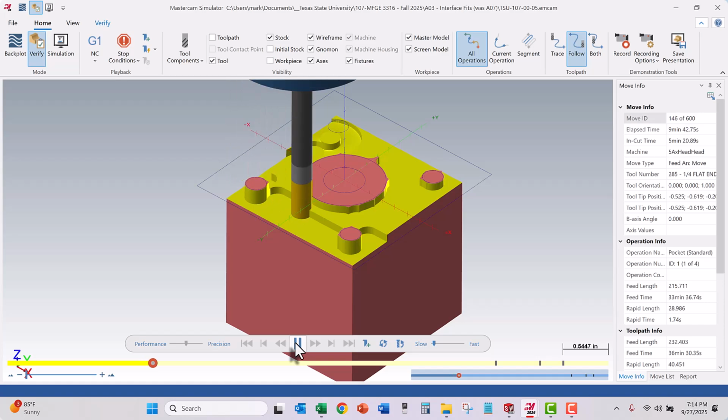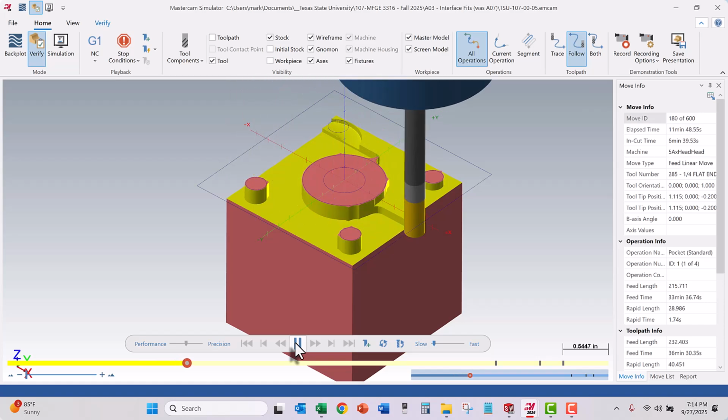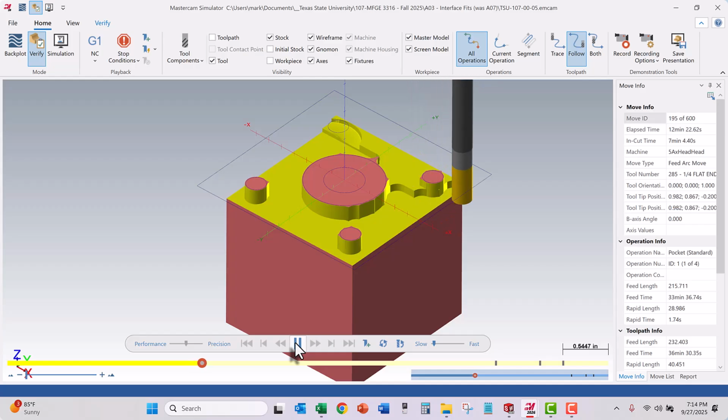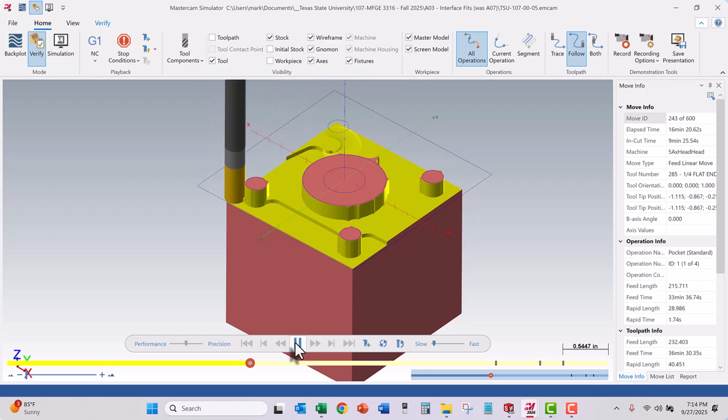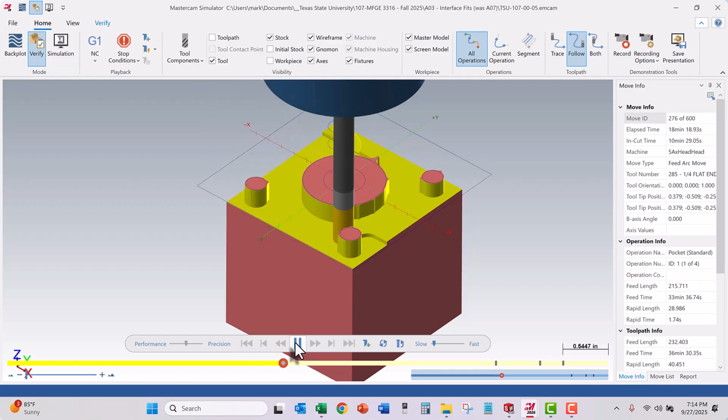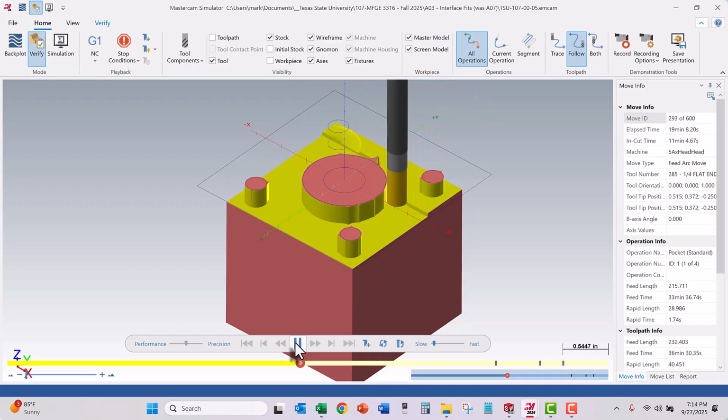Approximately, I told it not to go more than 1/8 of an inch on the roughing passes. Might have bumped that up. I don't know that I needed three roughing passes. There's a third roughing pass. I probably should have bumped up that 1/8 inch number so it only gives me 1 or 2 roughing passes, since we're just cutting this ring shaped material. And here comes the finishing pass, that 050 finishing pass to get all those surfaces cleaned up. It's going down and taking care of that.